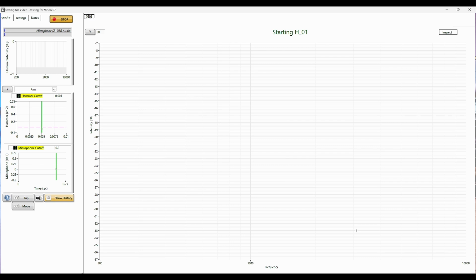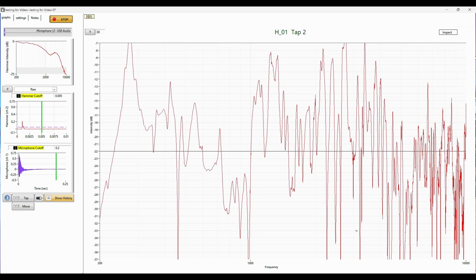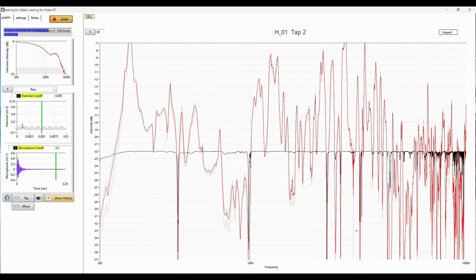As soon as you excite an instrument the second time in a given measurement, another function will show up next to the actual measurement result. This is called the coherence function, and what it is basically a mathematical comparison between the individual signals we are creating with each excitation. If they are identical, the value of the coherence function will be 1. If they are very different, the value of the coherence function will be closer to 0.